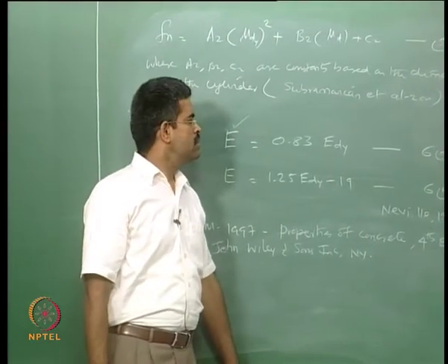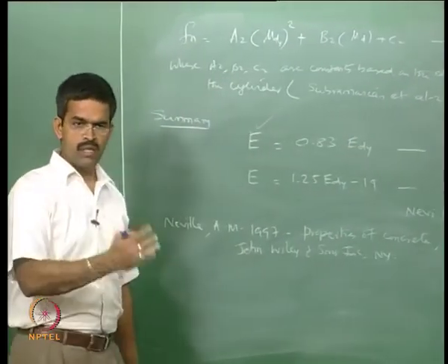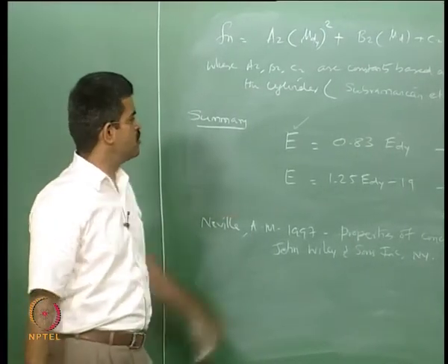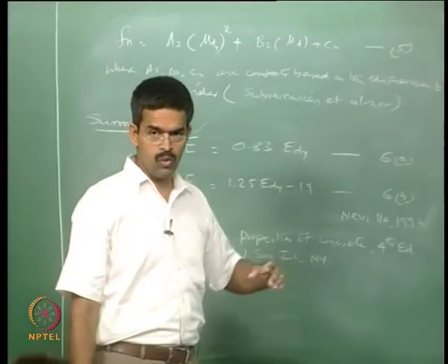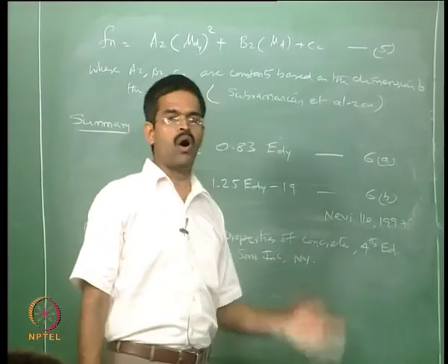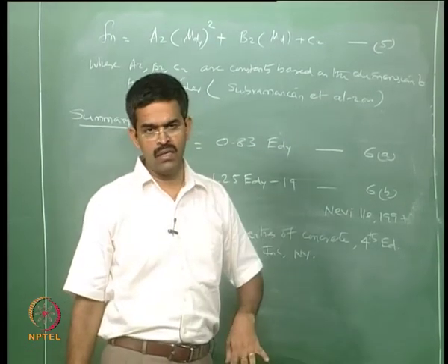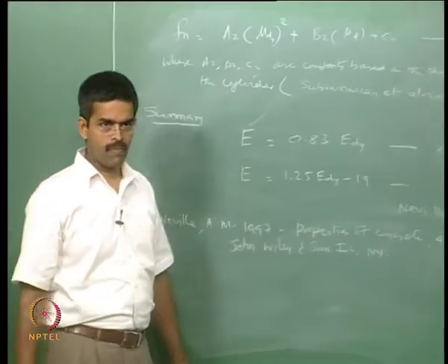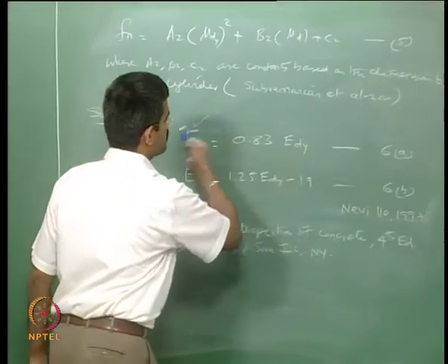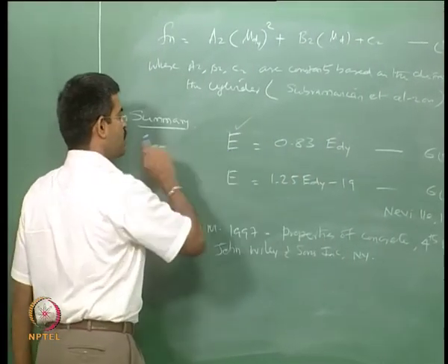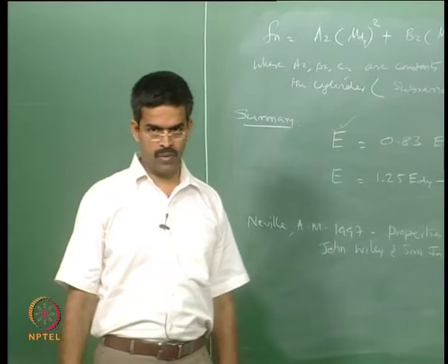Okay. So, one should strictly use dynamic modulus of elasticity in estimating the parameters of the design, where we are using static values. So, this is one important uncertainty which comes from group number 2, which influences group number 1 on a specific type of uncertainty, which is an important parameter in reliability studies. Okay. So, it is very important that we know approximately what the variation is, comparing the modulus of elasticity with the dynamic modulus of elasticity. Okay, there is a variation.